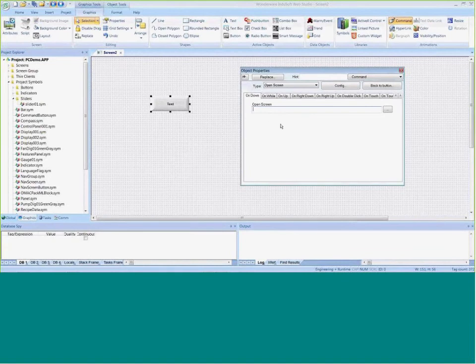And this is one of the nice features of InduSoft Web Studio: you can take advantage of these really nice interfaces, or you can get more powerful and get as complex as you want. So, for example, I could change this instead of being just the open screen command animation. If I wanted to go back to VB script, I could do $, open, and then put my parentheses. And if you notice there, I've got the IntelliSense that shows me the parameters for that open command. And you can see at the end, the ID and the mnemonics list. So that's essentially how you would use that.